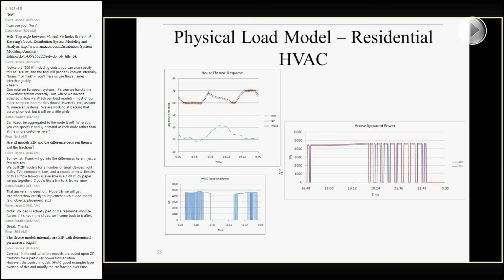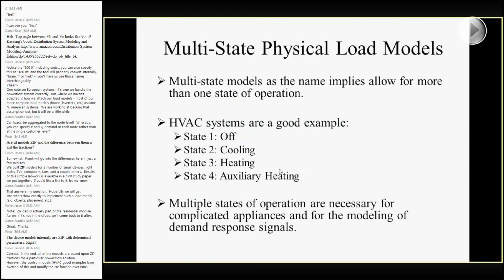Yep, very true. And I will caveat that with, even though they all do get reduced down to a current injection, that current injection is being updated on each pass of the PowerFlow solver. So the particular current injection isn't fixed to whatever your entering voltage was. It'll actually adjust with whatever the iterative solution voltage is as well. And we'll get into that a little bit more later in the presentation when we get into the different solver methods.